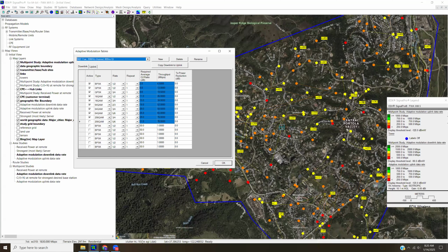And we don't give you a drop down with everything, because the drop down would shoot right down off the page if we included every solution provider and all the different modulation coding schemes that they use. So again, the best practice is to go ahead and reach out to the equipment vendor and find out the coding scheme that'll be used for this solution with this revision of their product, because even in the same product line, this can change.